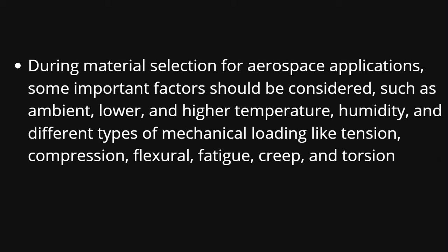If we use the material in a highly water-vaporized altitude, like high altitude flight, it is easily affected by water vapor. So we can definitely think about this main criterion. And different types of mechanical loading like tension, compression, flexural, fatigue, creep, and torsion. As usual, you already know about tension load, compression load, and flexural load. Fatigue is the starting and propagation of a crack. It is very important, because once fatigue forms and goes to the crack portion, the material easily fails.